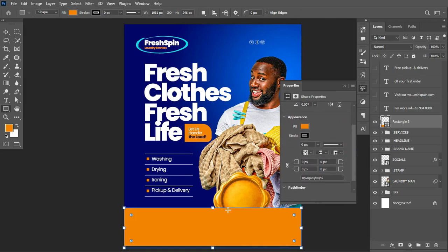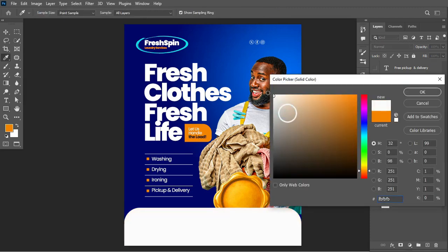I don't want to add the curve around everywhere, I just need to add it on one side. So I'll come over here, scale. You see what happens? It allows me to scale one end at a time, because this is not selected. So this is 96, this can be set to 96 as well. Change the fill color, I can just double click in here, change it to white.